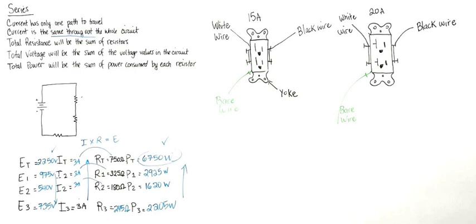Now for the other receptacles that are around your counter, those are general use. So those are for small appliances, like the blender, the coffee maker, the toaster, or anything else that you want to connect. But there are some people that run 15 amp circuits for those kitchens. We never run 15 amps for receptacles. We always run 20 because that gives the customer a better circuit. So if they connect the toaster, the coffee maker, and the blender, their breaker's not going to trip, because we left them a good circuit, so that they can connect all of their small appliances. But that's up to you, because the amperage of the circuit is not really something that the code goes into in certain areas, but,